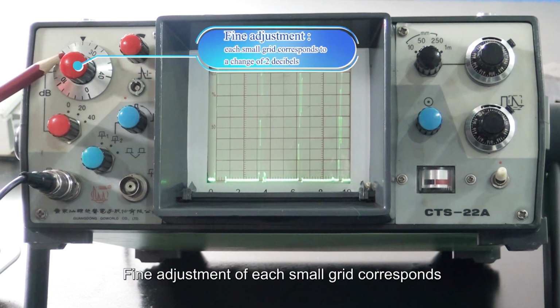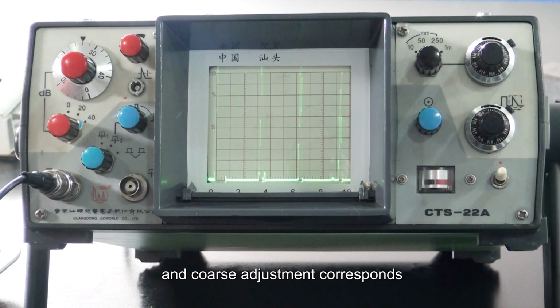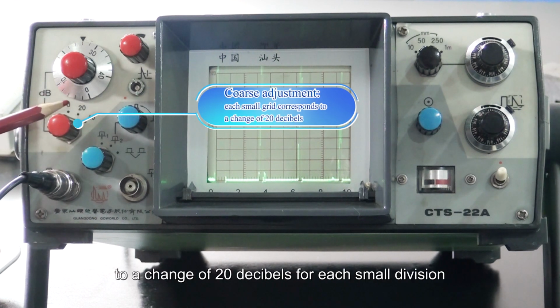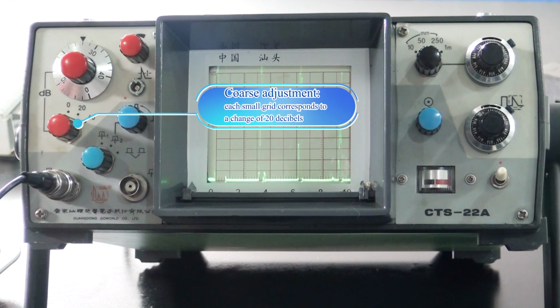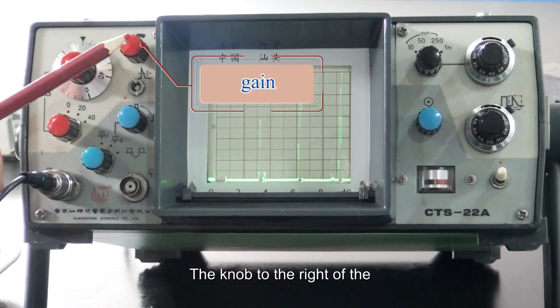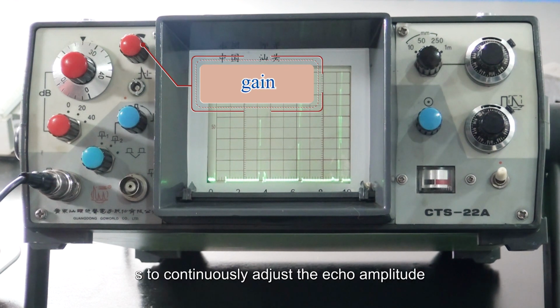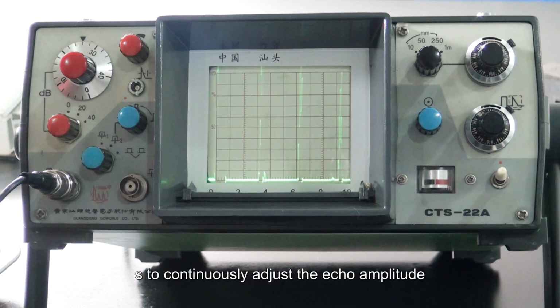Fine adjustment of each small grid corresponds to the change of 2 decibels, and coarse adjustment corresponds to a change of 20 decibels for each small division. The knob to the right of the attenuator fine adjustment knob is called gain, and its function is to continuously adjust the echo amplitude.